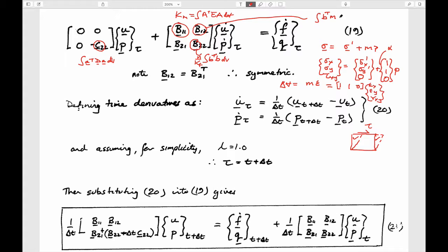But I digress. This was equal to the A matrix, dV. And we didn't really say that we'd seen anything like this particularly before, but we have. When we looked at groundwater mass transport, you might remember that we had a matrix that looked like the derivatives of the shape functions times the advective velocity times the shape functions, and the derivatives of the shape functions. This was the advective term.